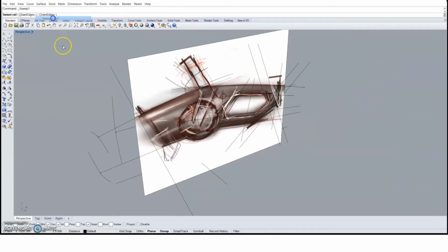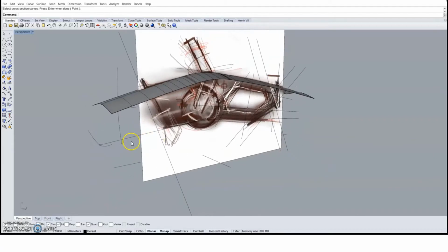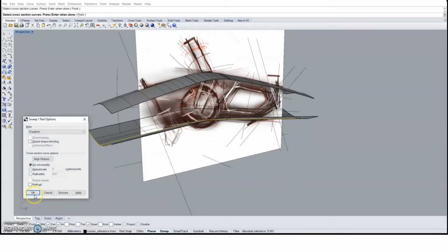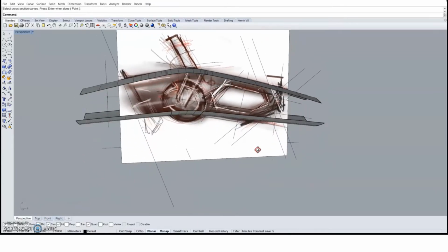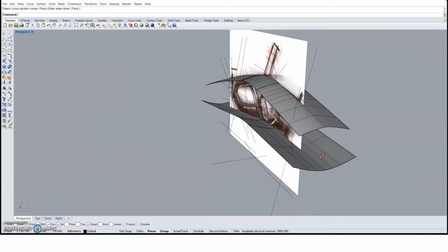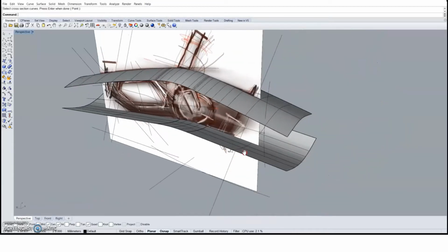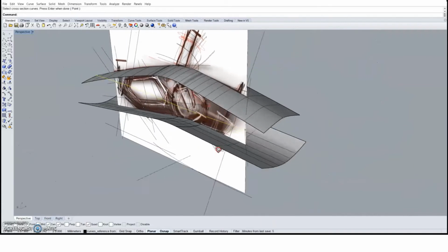And so we work between the 3D image and 2D image in our perspective window so that it's easier to see what we are doing most of the time. So we toggle between 2D and 3D as we are constructing the surfaces. And you can see how fast it could be once you have the curves, and then we create the individual surfaces, and later you see how we trim them and join the surfaces to become the main body.